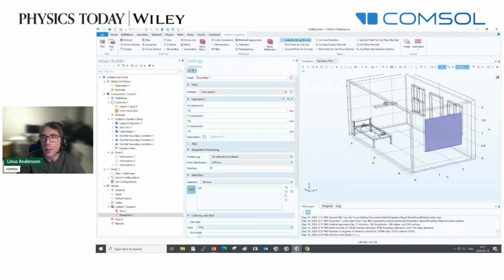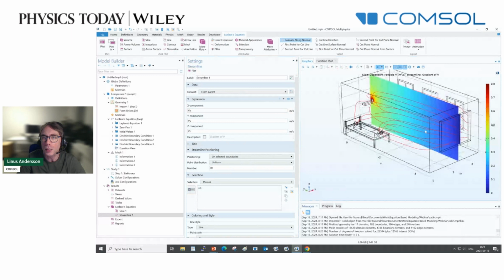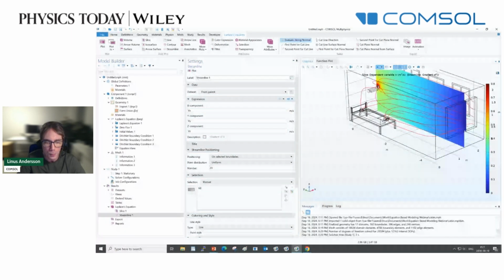If I click plot now, I've got streamlines, and those streamlines will end up either on my skin or at the trap. And these streamlines actually now represent the paths that the mosquitoes would follow had they not been dealing with this random walk. If they were just completely following the attractor, following the scent, they would follow those streamlines. So we could, right now, if we wanted to, just count the number of streamlines that end up on the trap and the number that end up on me, and that would give us an idea of the efficacy of the trap, I should say.